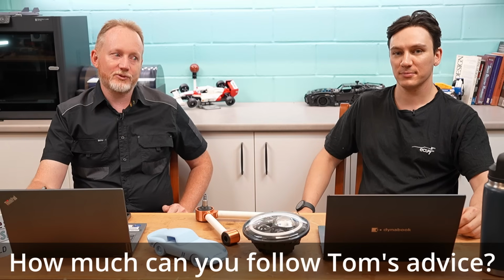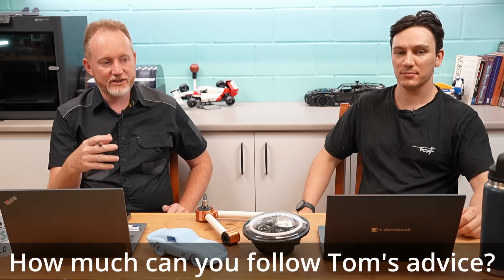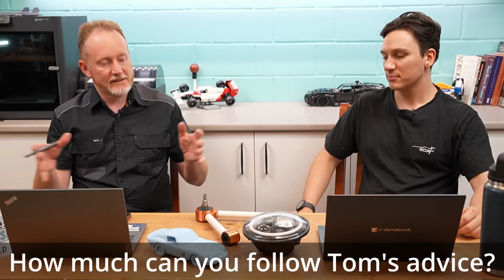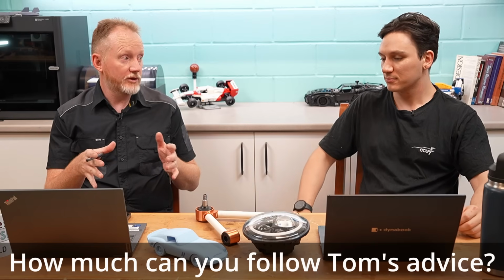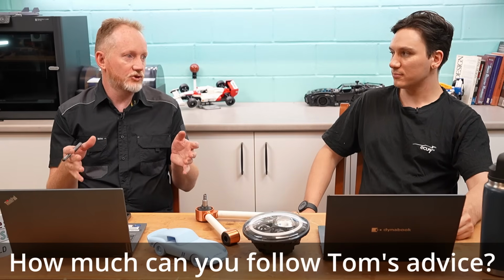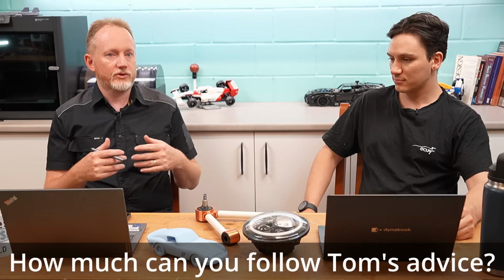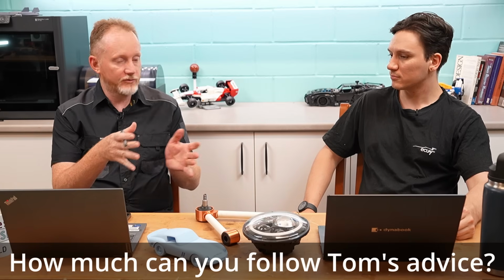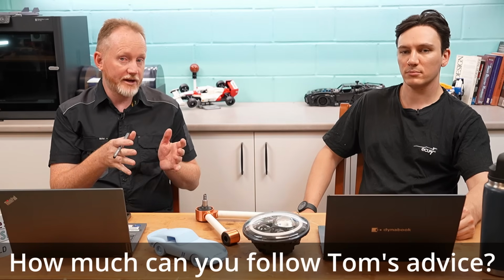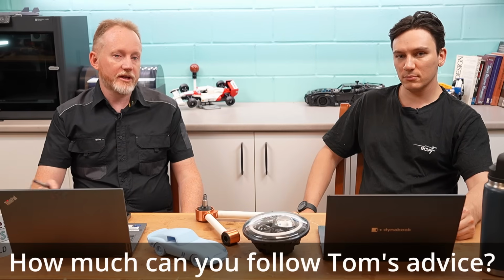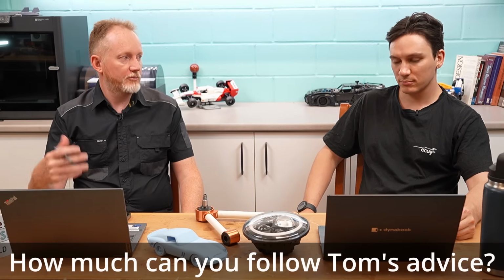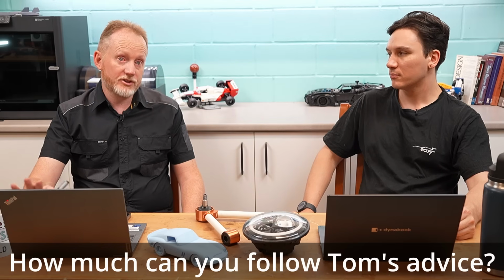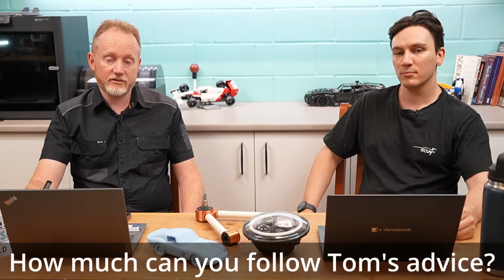I think the biggest issue with the diffuser section is probably not dodging around the engine and gearbox, because even though it's a flat 4 that we're looking to do, where the width of the engine is, it's not far behind where the drivers are. So you're already wide in the car, and then it narrows up around the gearbox quite narrow, so there's space there for the diffuser. The bigger issue will be the lower wishbones poking through the diffuser, and so I'm not sure. I've got to go back to the model. But pretty much everything that Tom suggested, we're going to try and implement.